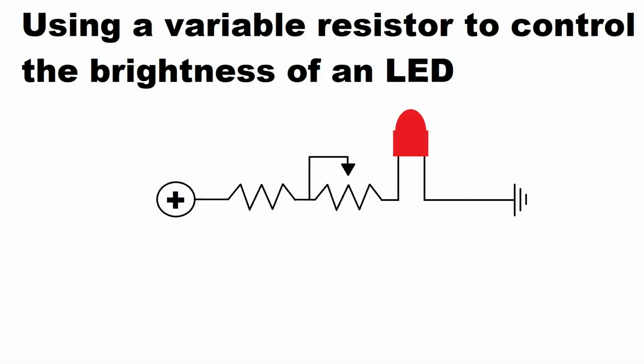If you do this, you will still need a small resistor in series with the potentiometer and the LED, because if you don't, then the LED will burn out when you turn the resistance all the way down on the potentiometer. Without that protective resistor in the chain, direct voltage can also damage the potentiometer.